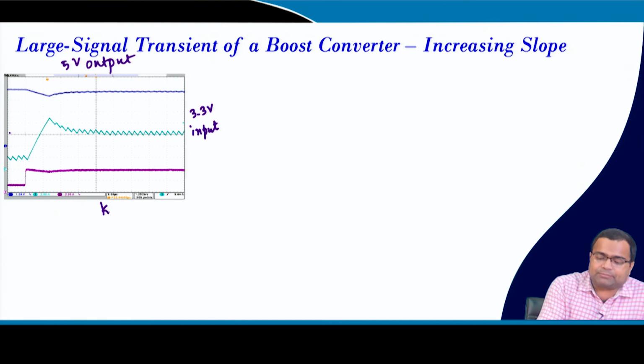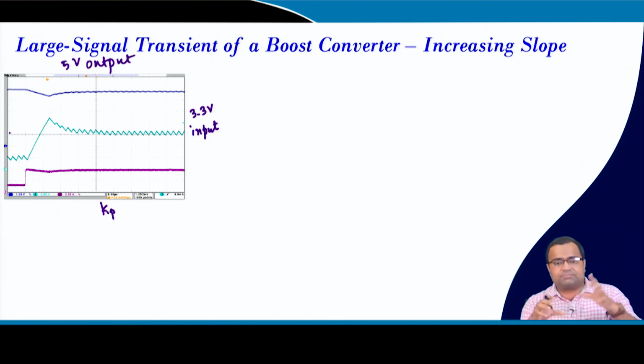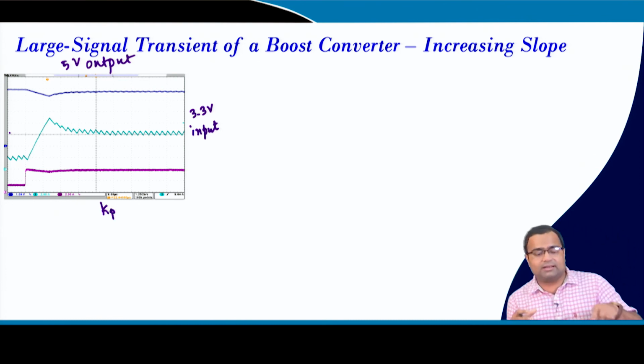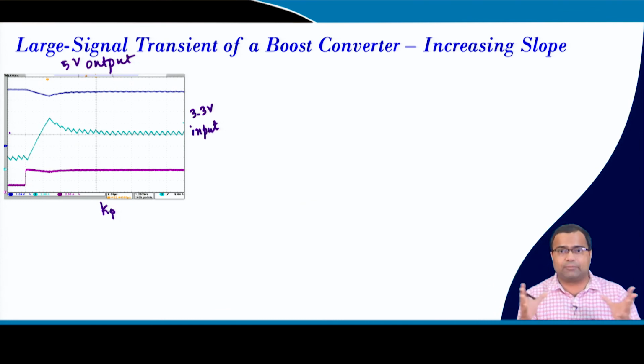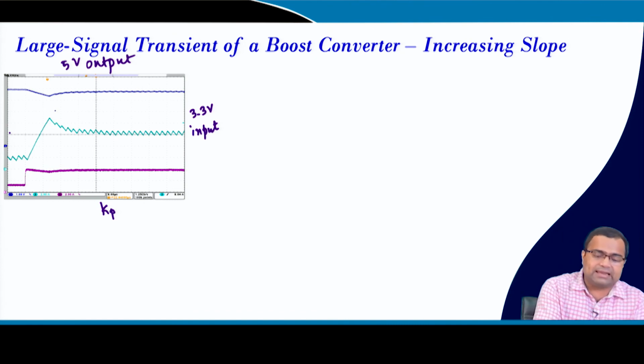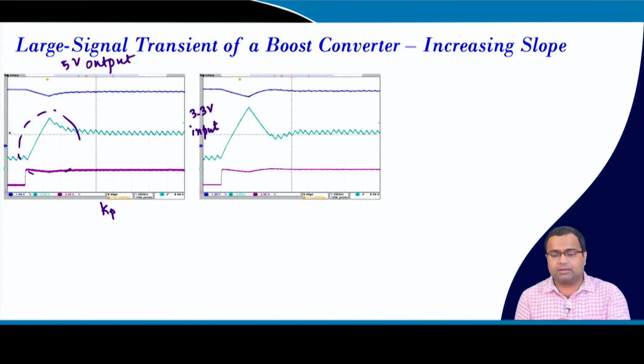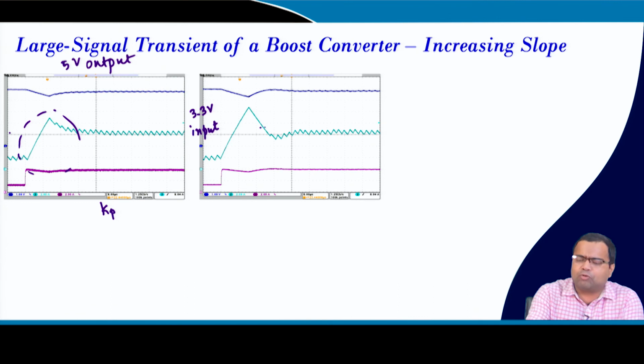Here we take a smaller Kp because I am just playing, but we will formulate for the buck converter more elaborately, and we will give an expression for boost in the subsequent lecture. But what we did by this formulation, if we take a smaller value of Kp, you can see it is not the optimal recovery because there are a few more switching numbers.